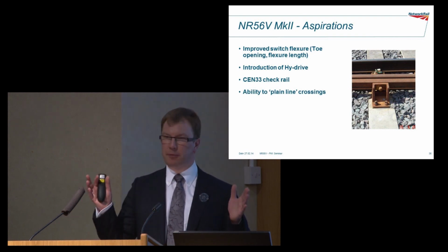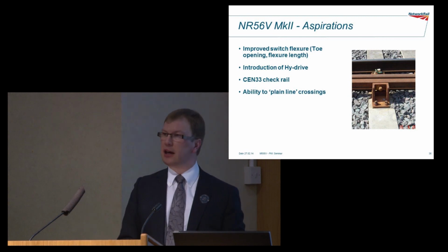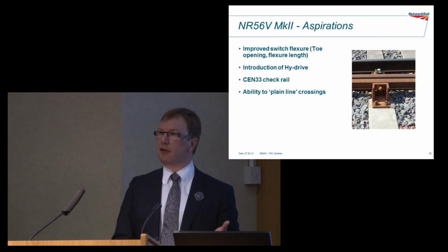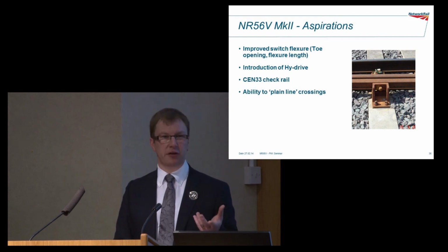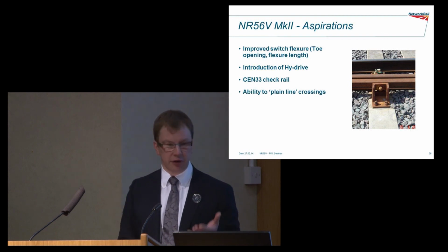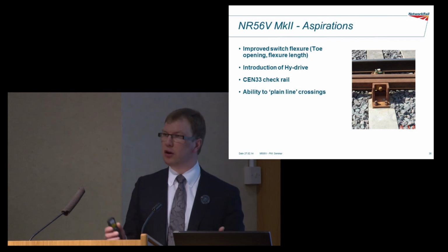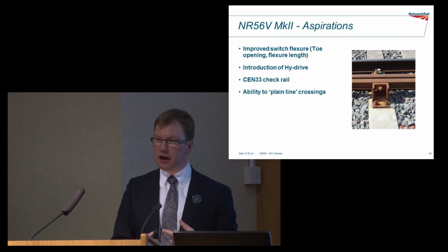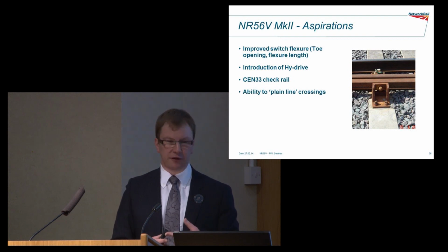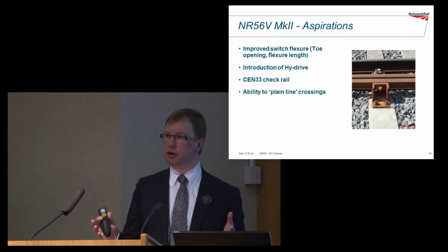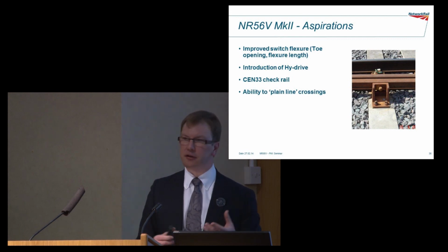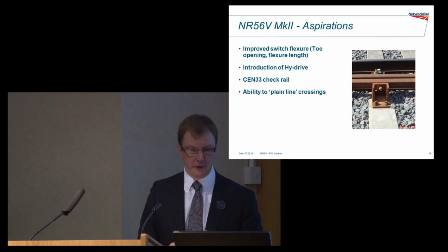I've already said before about needing to keep the same footprint, but we're learning an awful lot more now about drive forces, about frictional coefficients of slides and everything else, just understanding what makes the switch work, and there may be some things that we need to do to make the switch operate more effectively. Shallow depth switches, particularly the shorter ones, are very stiff and it takes a high drive force to operate them. So that's something we need to address going forwards.